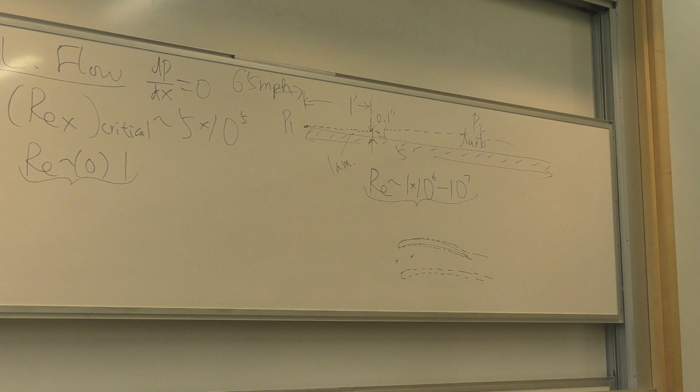There's a name that goes with that from last time? Pressure drag, or we call it form drag or shape drag, because it's very much a function of the shape of that object. Like a fish, a streamlined shape, a missile has very little form drag. But the longer the object, the more shear you have, and the more frictional drag. So as an engineer working for Boeing, you're trying to design an airfoil that is optimum, minimum form drag and minimum shear drag. And then you will have less power required from the engine to fly at constant speed. There was another question? No.